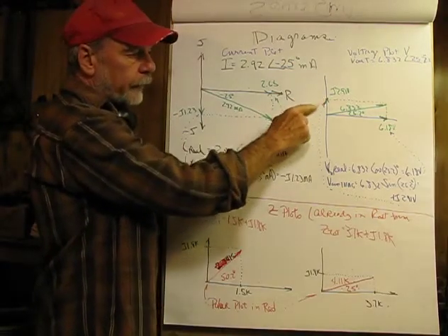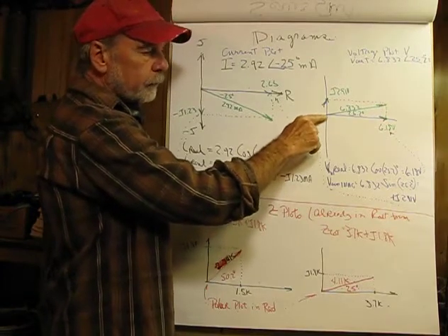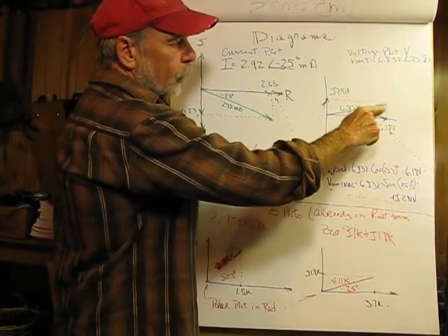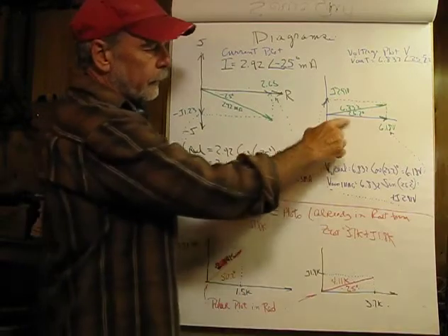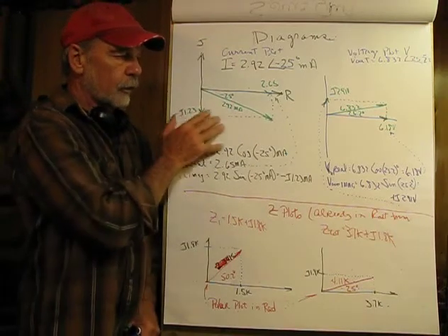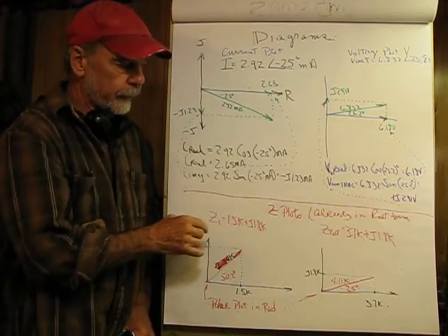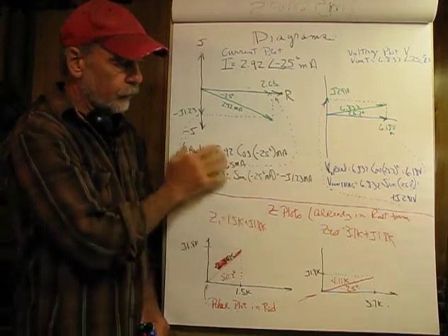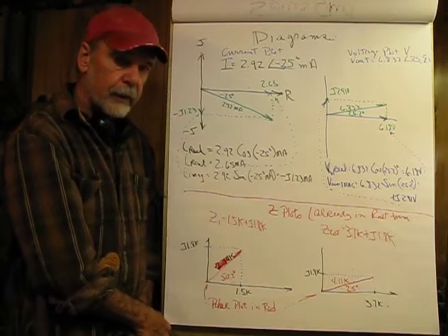So I'll put that phasor there, and then connecting the dots again and drawing the voltage phasor in polar form would give us a 6.832 that we had before, and in the angle there we see our 25.2 degrees. Now in these diagrams I don't have a grid per se, so these aren't necessarily going to be exactly in the right dimensions, but as long as you get the math and as long as you're working with paper that has a grid, you should be able to make pretty accurate plots.